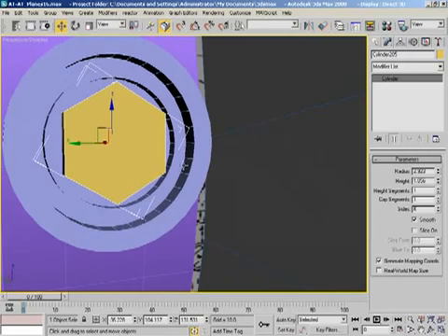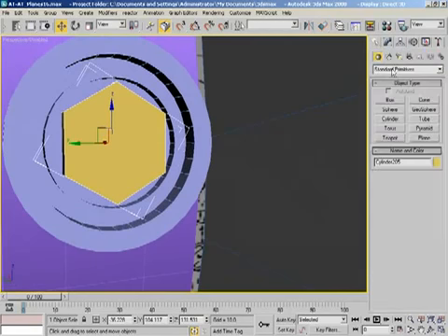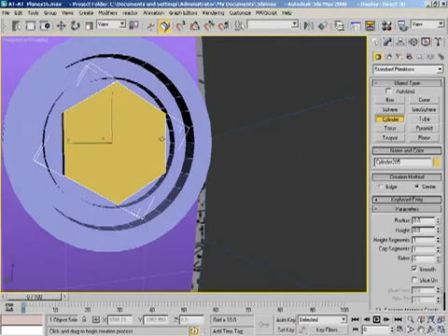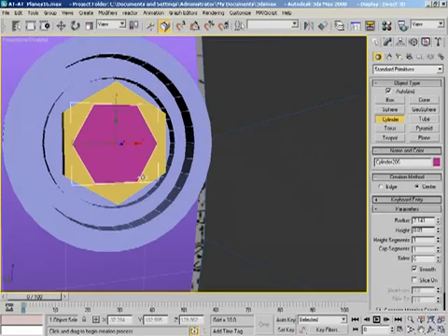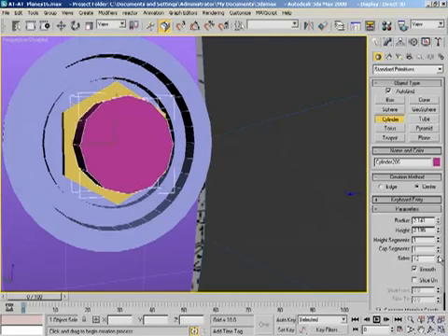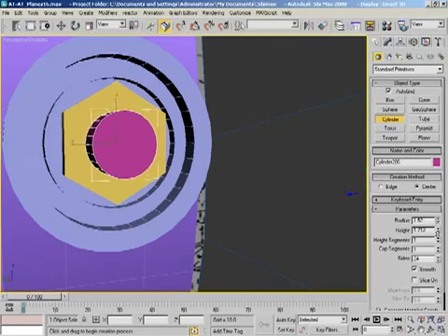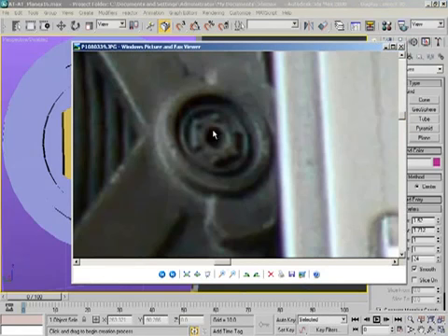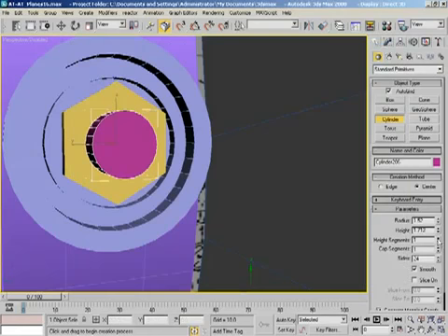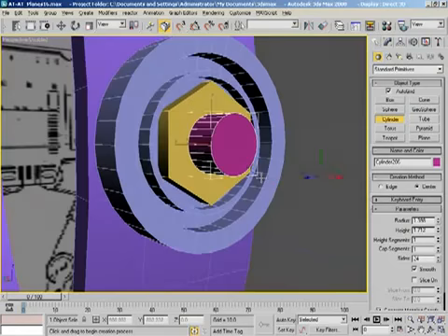Okay, now, almost done. Let's grab the Create Cylinder button yet again. Now, if we really wanted to, we could just switch on auto grid, and we could drag one of these out like so. Again, give it some magically arbitrary amount of height, and kick this up until it's circular again. So 24 looks pretty good for the size I'm chasing, and then we could pull down the height. We can definitely pull down the radius, and what I'm doing basically is creating this circular indentation that goes right here in the middle. So if you're curious. So pull down the radius, maybe somewhere right in here would be good.